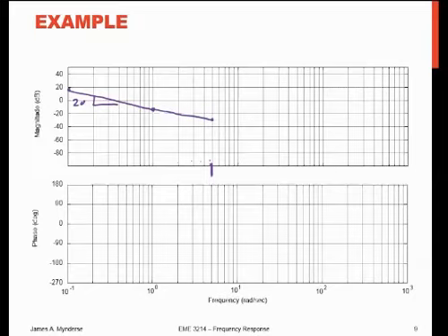So I end up with a, no, it does not. It's a complex 0. It has a slope of 40 dB per decade up, because there's two poles there. It's complex. And so 40 dB minus 20 leaves me with a 20 dB increase here. And I'm just not even going to try and draw this to scale. And I also know I have my peak of that 14 dB, and it's just a little bit to the left, and it's going to go like that. So now this is a plus 20.